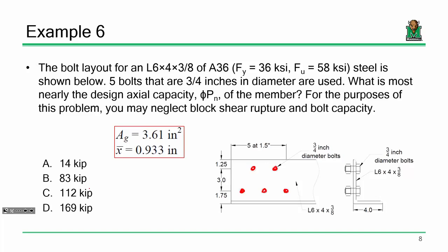So what, y'all steel design folks, what pops out to you? Stagger factors, because the bolt pattern is staggered. Your failure path is going to look something about like that. Because if I take this angle and I pull on it with some force P, it's not going to just samurai sword straight through. It's going to fail along the bolt lines. You remember that? So in order to do that, you need all the dimensions, you need the gauge factors. Then this is an angle. Angle properties aren't in the manual, so you need Ag and you need x bar.